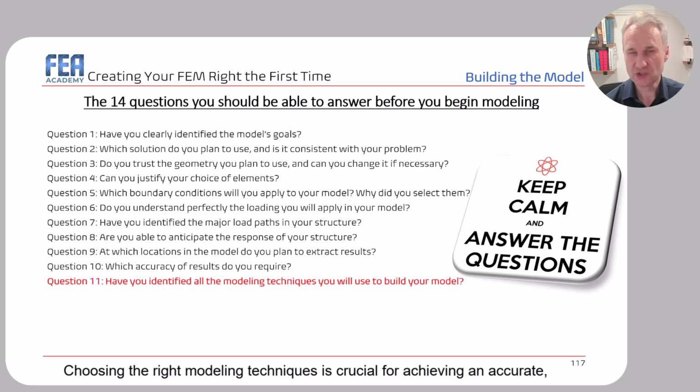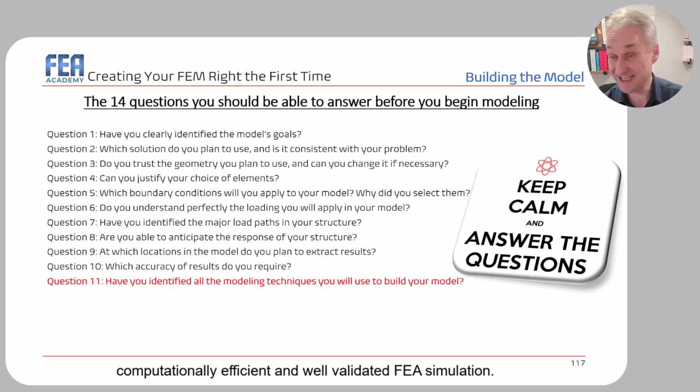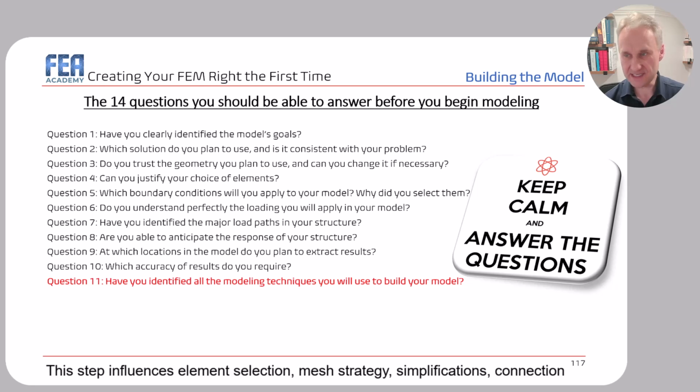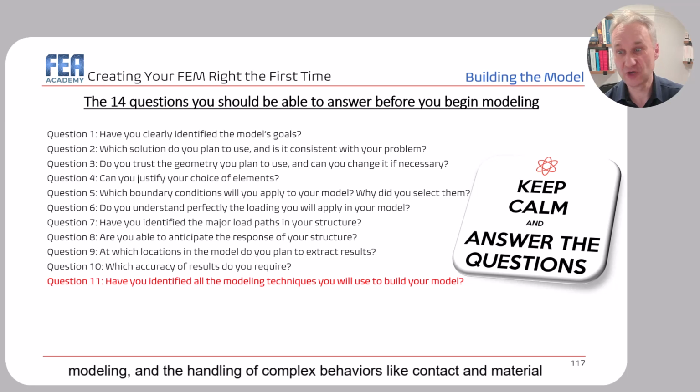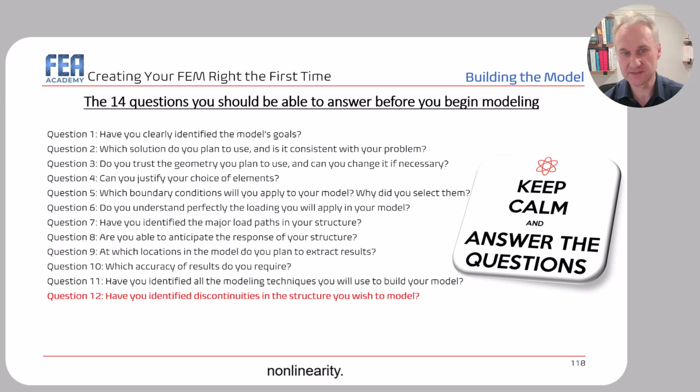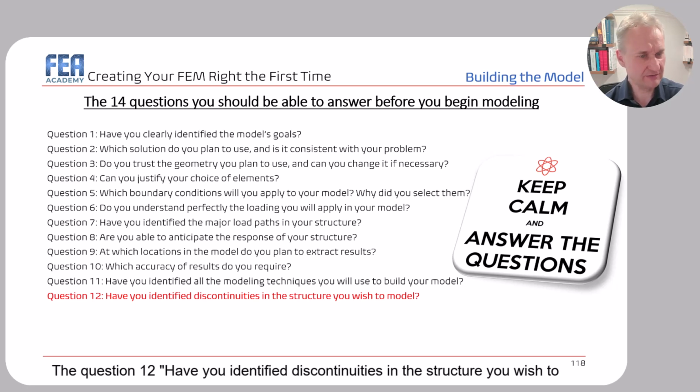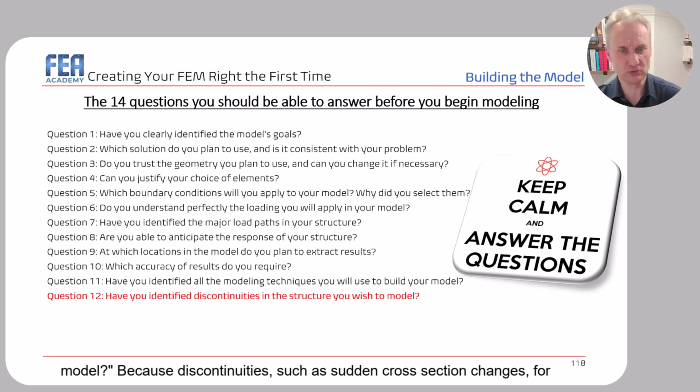your model? Choosing the right modeling techniques is crucial for achieving an accurate, computationally efficient, and well-validated FEA simulation. This step influences element selection, mesh strategy, simplifications, connection modeling, and the handling of complex behaviors like contacts and material nonlinearities. The question 12, have you identified discontinuities in the structure you wish to model?